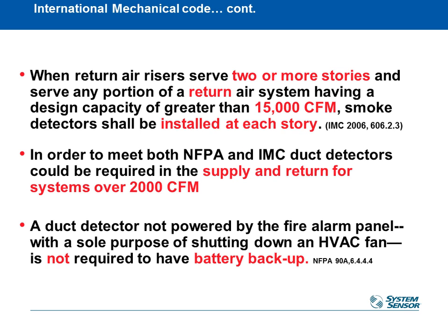So that kind of gives you the summary of when you have to do this by code. Basically 2,000 CFM, you need to put one in, either the supply or the return duct, depending on which code you're going to follow. 15,000 CFM, you need to do it on both.